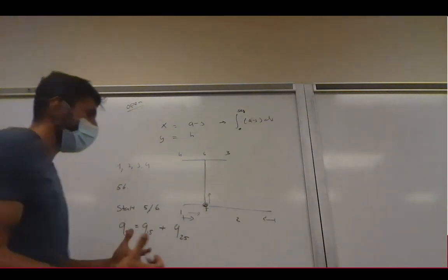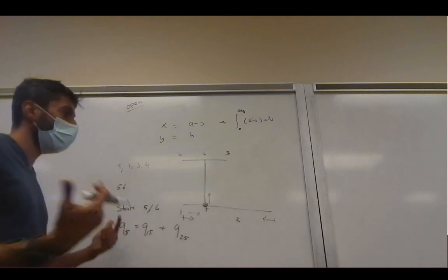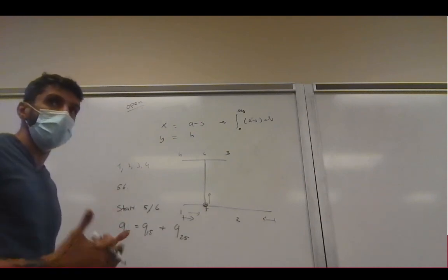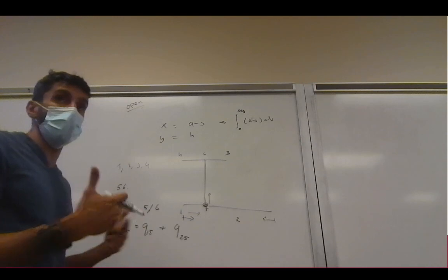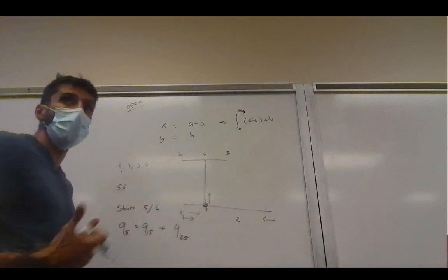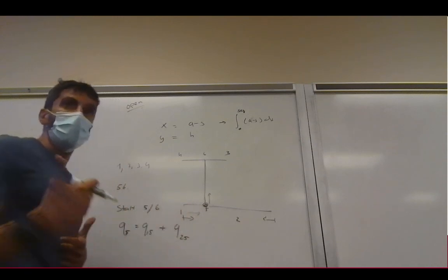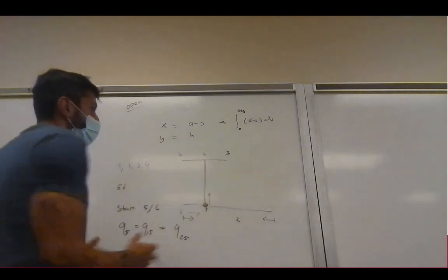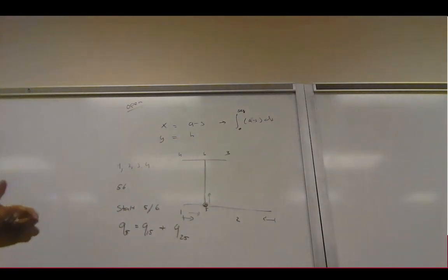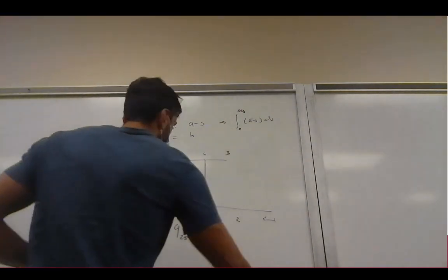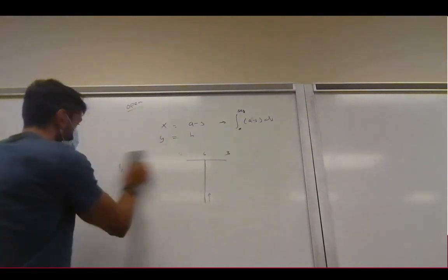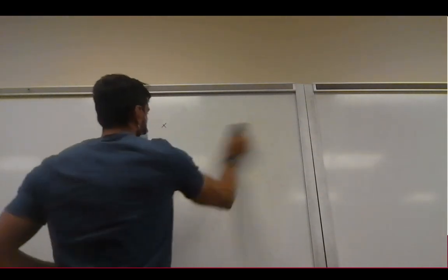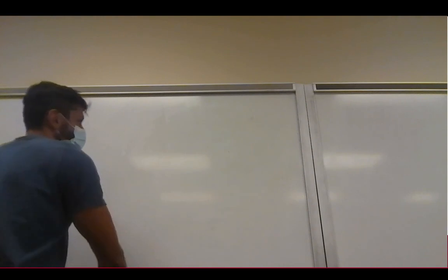Basically, whenever you have an intersection, you have to come in from all the free edges first and calculate what the shear flow is at that location before you can continue, because you need that point before you can continue to segment 5, 6. So you need to know what the total Q5 is before you can calculate segment 5, 6. So keep that also in mind. And of course, always try to apply symmetry where possible.